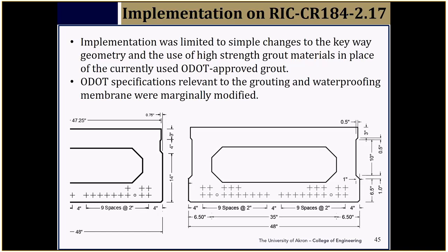The moment there is a crack and the joint has failed, then the transfer of load is not happening and therefore it won't work. So deeper joints will reduce the tensile stresses and therefore the tendency to crack in the first place.